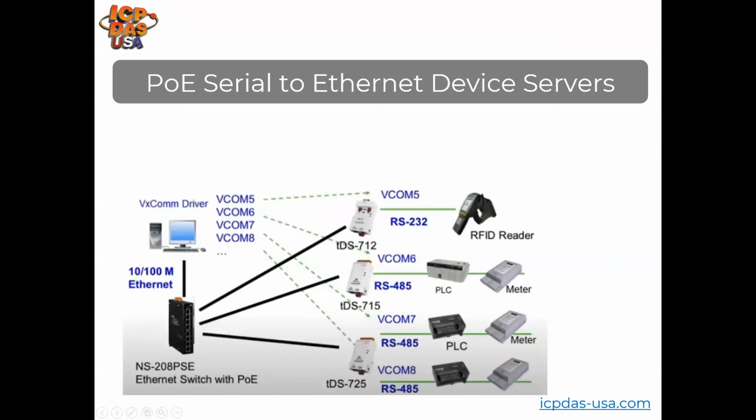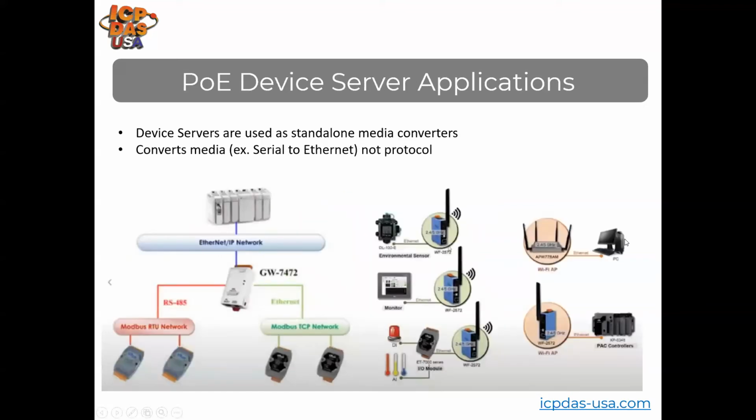These can be powered over Ethernet, this TDS series. So you can power them with power over Ethernet switches or other kinds of power sourcing equipment. These kinds of device servers, like I mentioned, the Ethernet IP-based PLC, you can use that to control different Modbus devices. So it's really helpful for integrating different systems together.